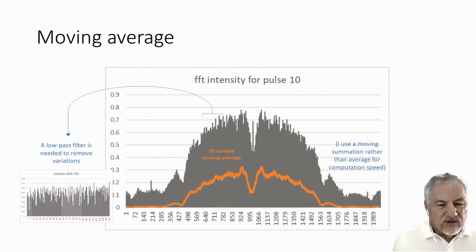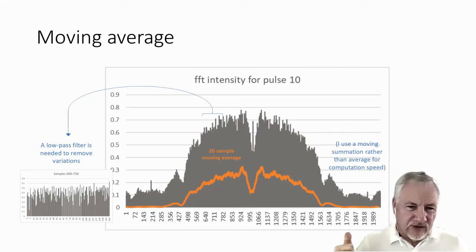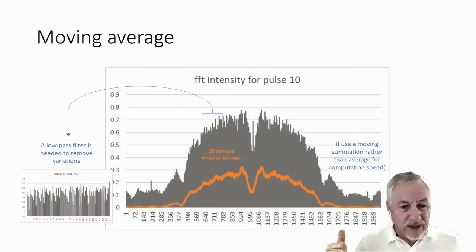And so we can't just look for a sample that's close to zero as our threshold. So instead, we must do some sort of averaging. I show you in orange the average of these, and you see that it's much lower. The reason it's much lower, of course, is because many of those samples are actually close to zero.